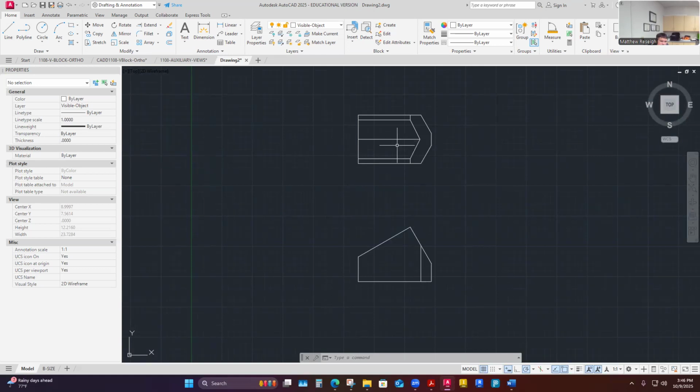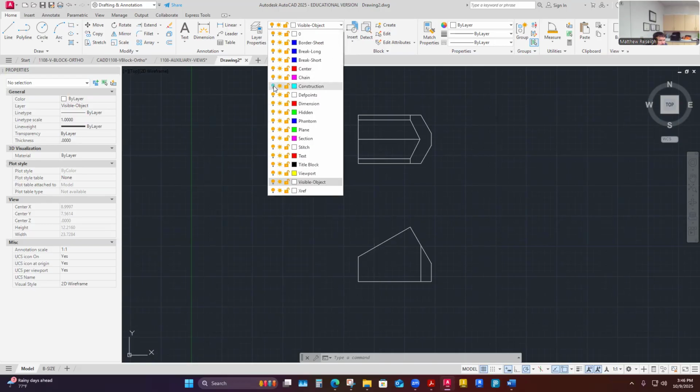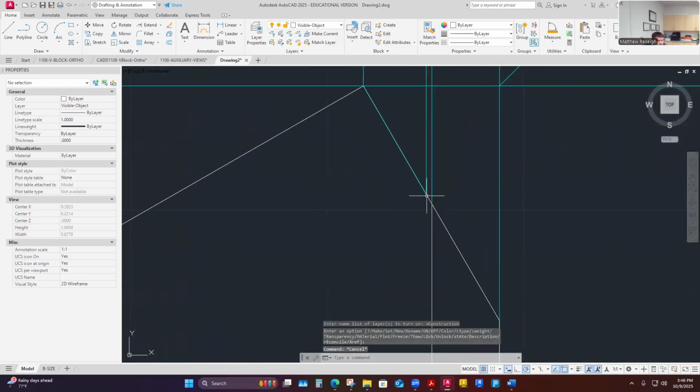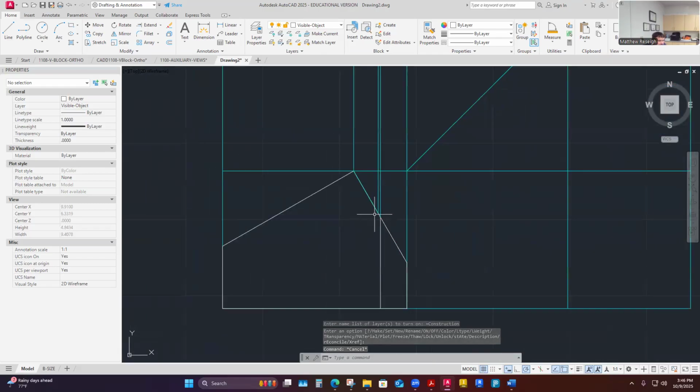So I'm going to do the hidden lines on the front view, and I'll just pull up my construction. The hidden line is going to be the bottom of the V, and then it's going to be parallel to the top surface right here, till it exits out this way, somewhere in this area. So I'm going to do an offset of this particular line.